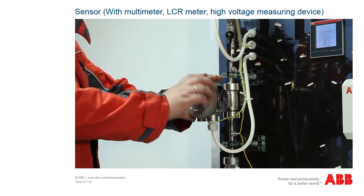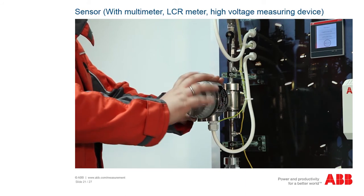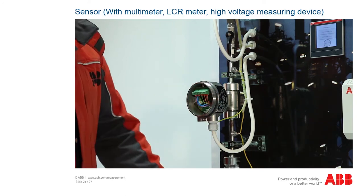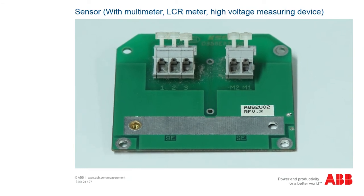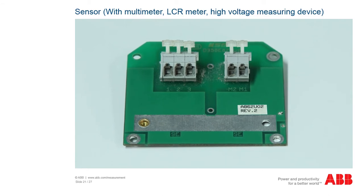Once you have checked the electronics of the flow meter sensor, you must check the sensor. We need the coil resistances, the insulation resistances, and the electrode impedance. To perform the measurement, you need an adapter plate, referred to as an XE board. You can order this from the ABB spare parts service.